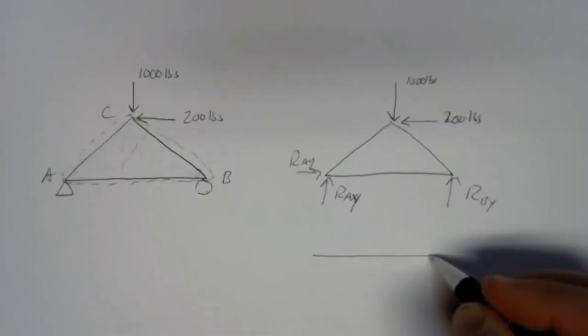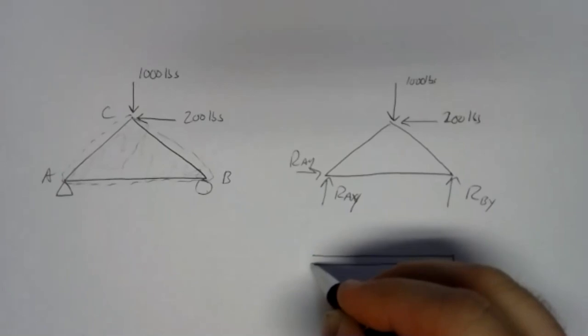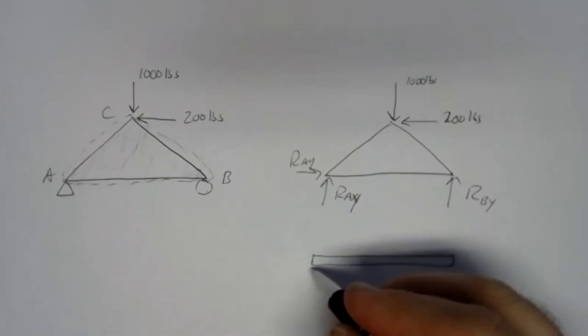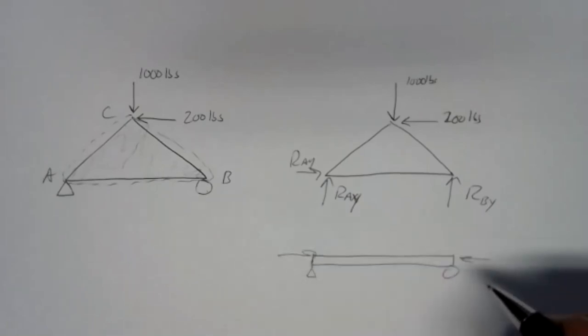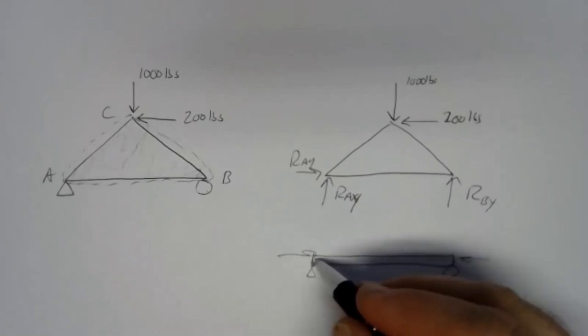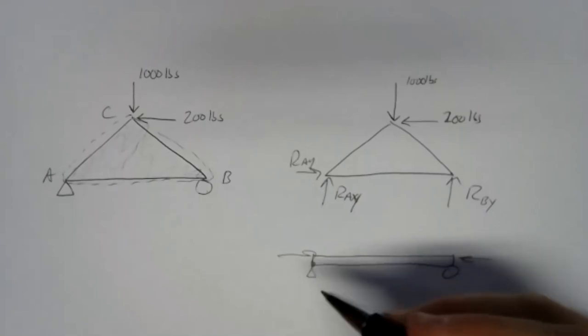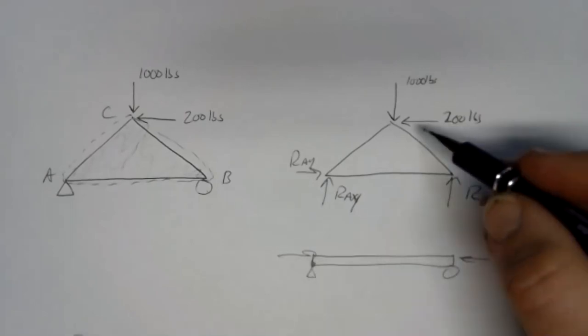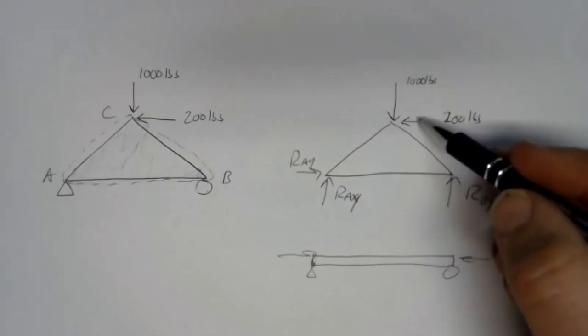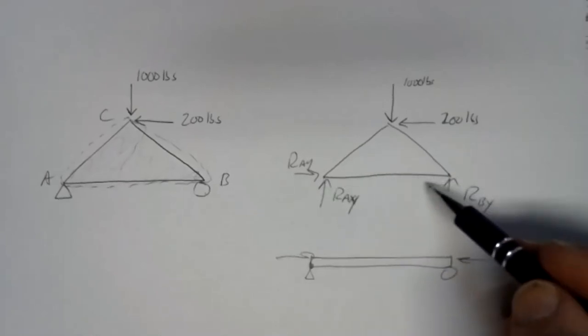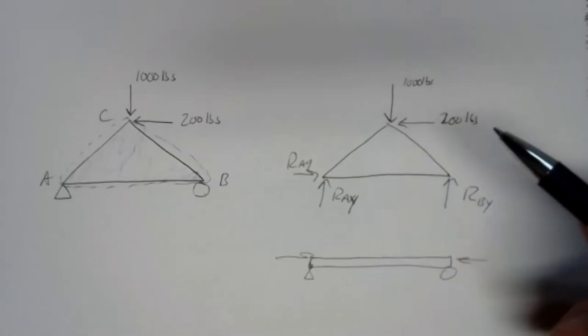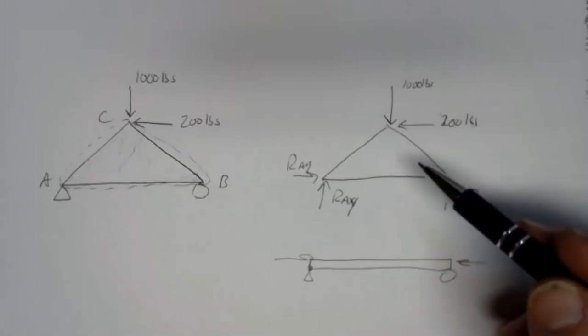In a beam problem, we just had something that was very thin compared to its length. So where we had our pin and our roller, it didn't really matter if we had forces to the sides. Those forces didn't have any moments, because if we were pivoting down here, there was a very small arm there, almost zero, so it wasn't worth considering. This could be feet of distance. In a typical roof structure, if this is 12 feet across, this could be 6 feet up. That'd be a common roof pitch.